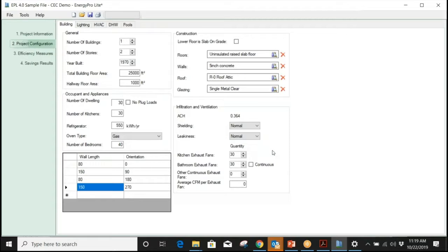Yeah, and on the leakiness, you're going to get a pretty good feel for that on site by talking to the facility staff and tenants and asking about their thermal comfort within the building. If they're saying it's drafty, if it's cold in spots even when the heater's on, you can pretty much assume that it's a pretty leaky building.